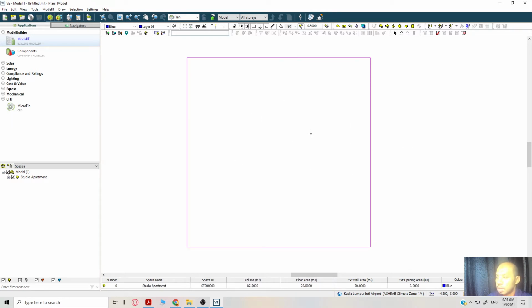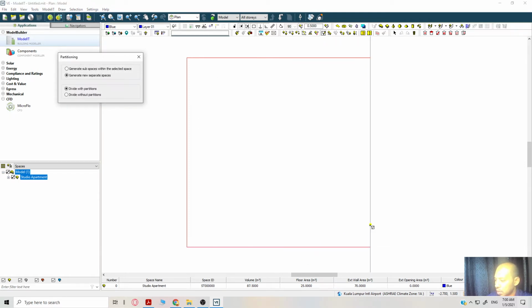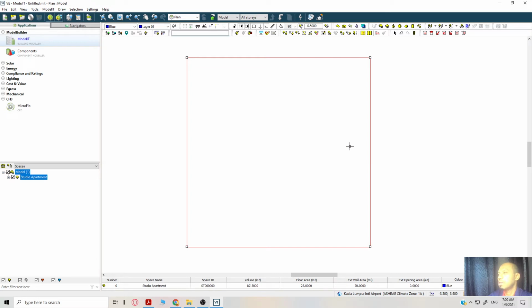in this object here. So the first thing that we have to do is to click this to select this model or this object, and we're going to use draw partitions to divide the selected space. So click here, and we already know the length. Oh, before that, despite knowing that the length is 2 meters and here 2 meters, there is no guideline to draw this partition. So I would suggest that to do this, what you need to do first is actually to create a construction line. So where is the construction line?